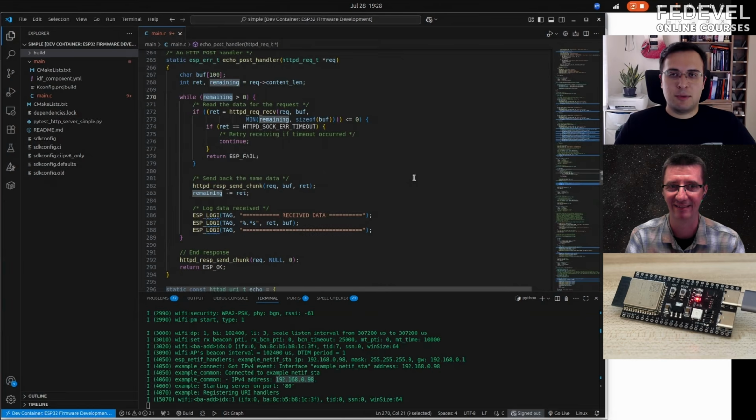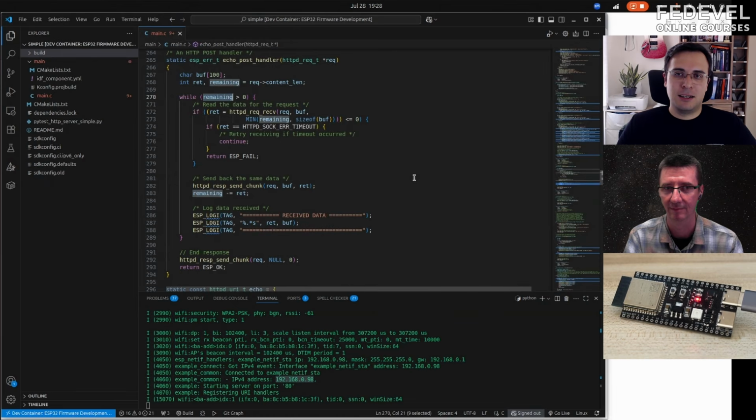Yes, the settings are important, because if you don't choose the right flash size or CPU frequency, the firmware doesn't run and it doesn't give you a clue. At the beginning, I tried to change some stuff, and it didn't work. So the Arduino debugging capabilities are a bit limited, but it's a good starting point.